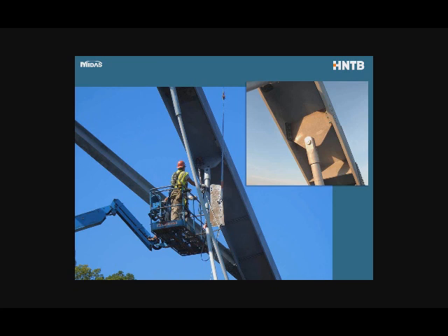And then the final step is the whole cable is lifted in place, as shown here. And then it's a very simple pin connection, just like what you've seen for the Happy Hollow Bridge. So with this system, much less work for cable connecting, but you need much larger equipment to stress if you have large cables. And of course you have to deal with the weight of the cable, and if you have to replace the entire cable.